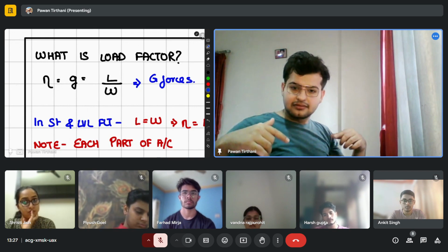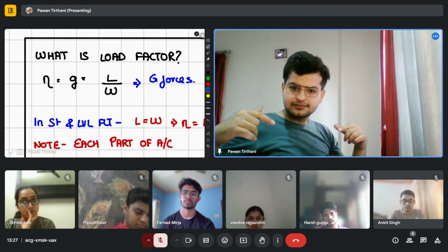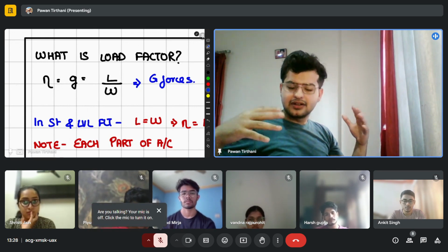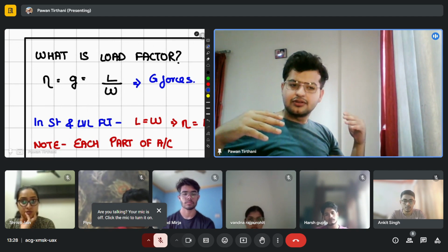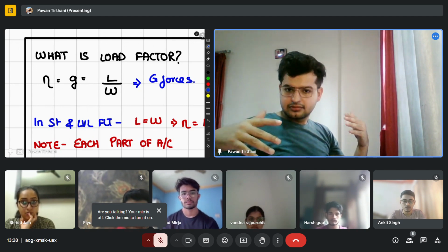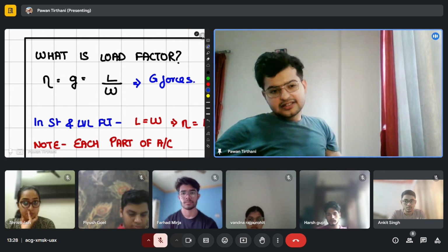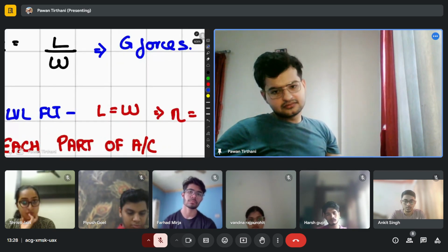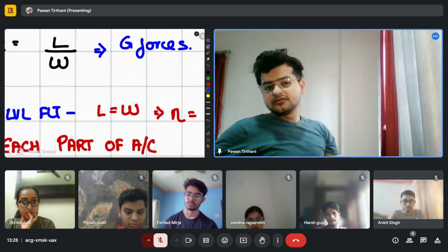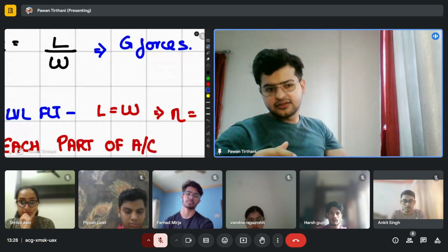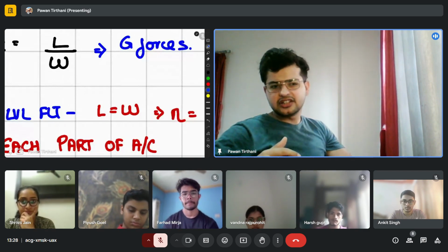-1 times of lift. मतलब if your aircraft's weight is 100, your aircraft can produce -100 units of lift. Basically negative. So in straight and level flight, do you guys agree that lift is equal to weight? Yes. So what is the load factor? 1. Just like you're sitting right now. So in an aircraft, do you feel anything? No. It's like you're sitting on a chair, regular chair.